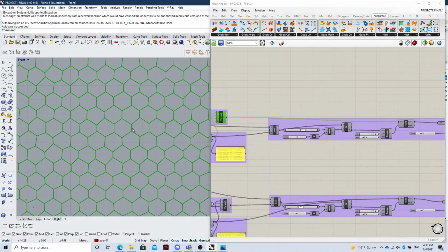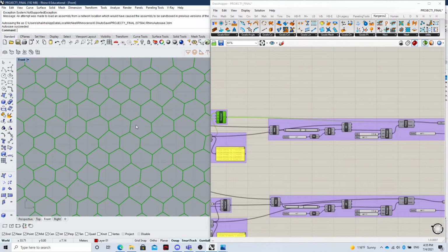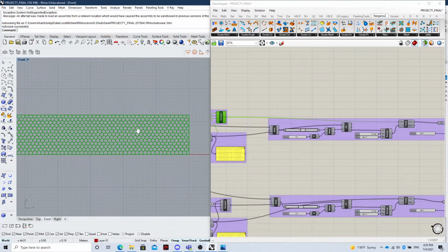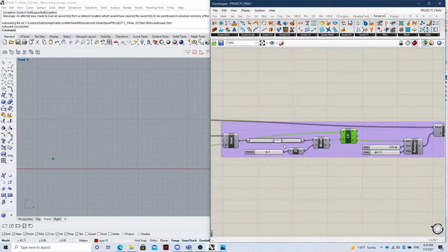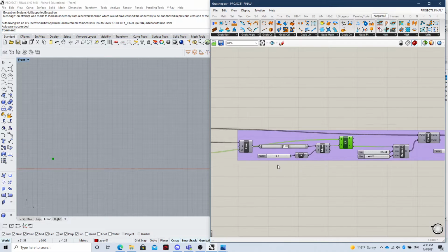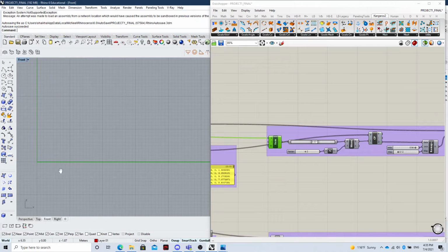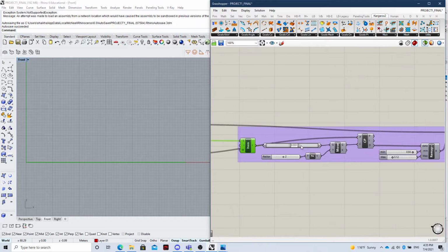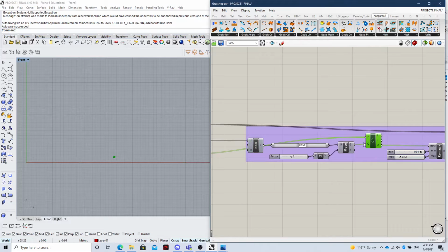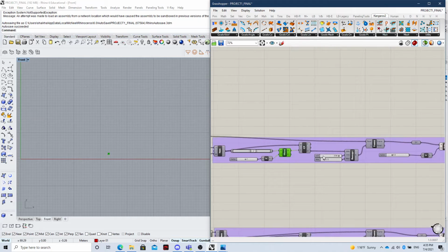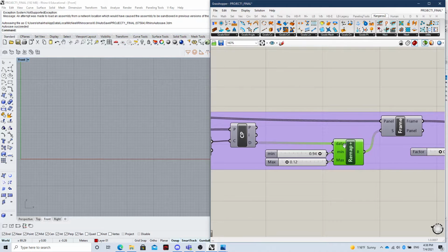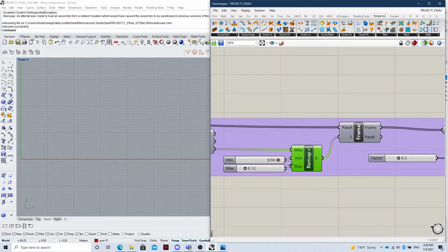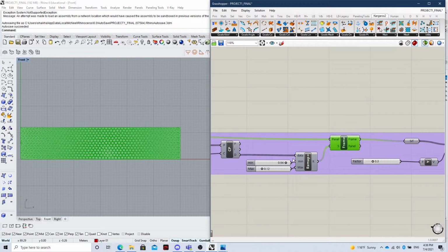And then after that, I wanted to create a variety in the offset of these Voronoi, which would be also parametric. So I used the closest point, and you can move this along, so I selected this line first from the original face that I had, then used the closest point battery as well as the move to move this point, and this movement would define how big or small the offset would be. So I used the remap in order to define what's the minimum and maximum, and that result.